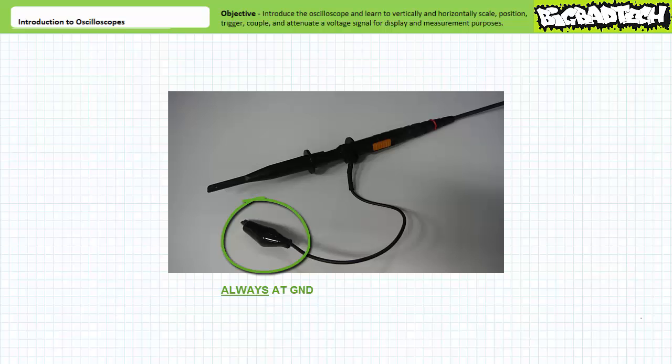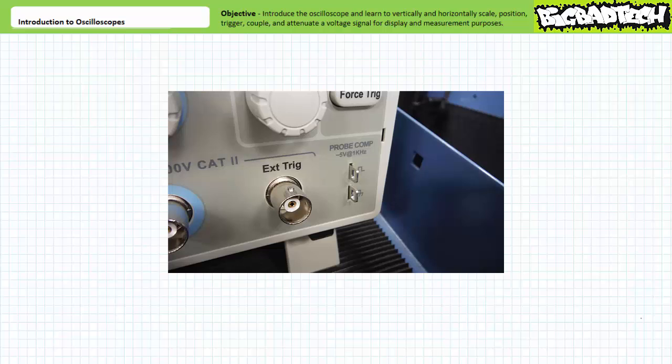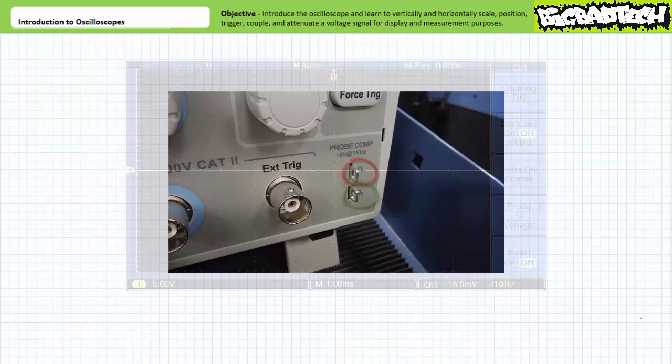This means that the simple act of touching something with the alligator clip ground references it, which, as we'll learn in later applications, may be a total deal breaker. For now, just consider the grabber as equivalent of the red lead of a voltmeter and the alligator clip as equivalent to the black, the caveat being that this black lead is always directly connected to ground. The test point conveniently features both the test signal output and a ground reference for test purposes.